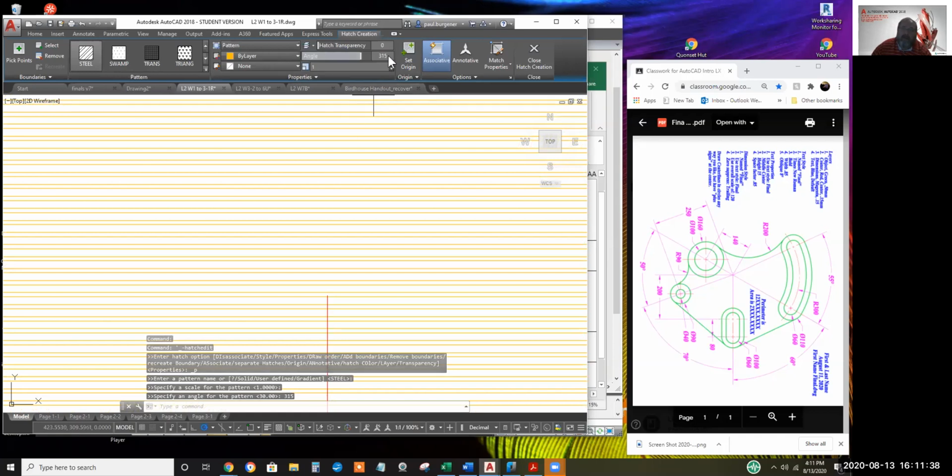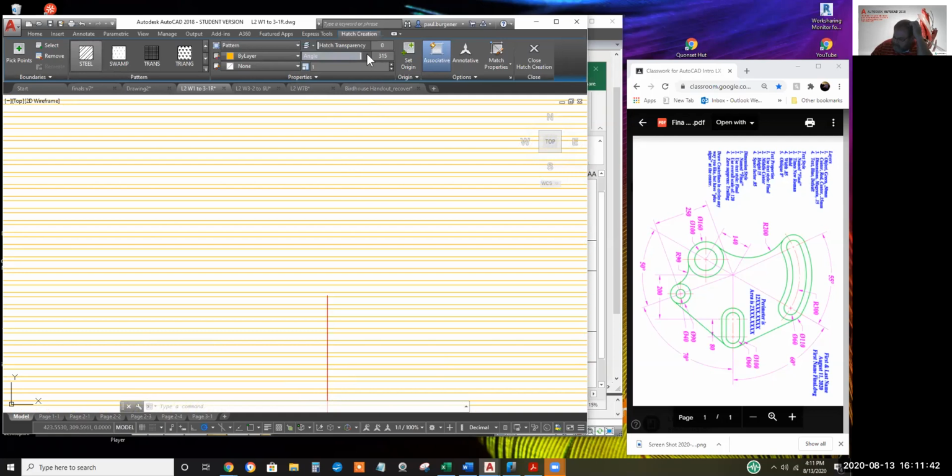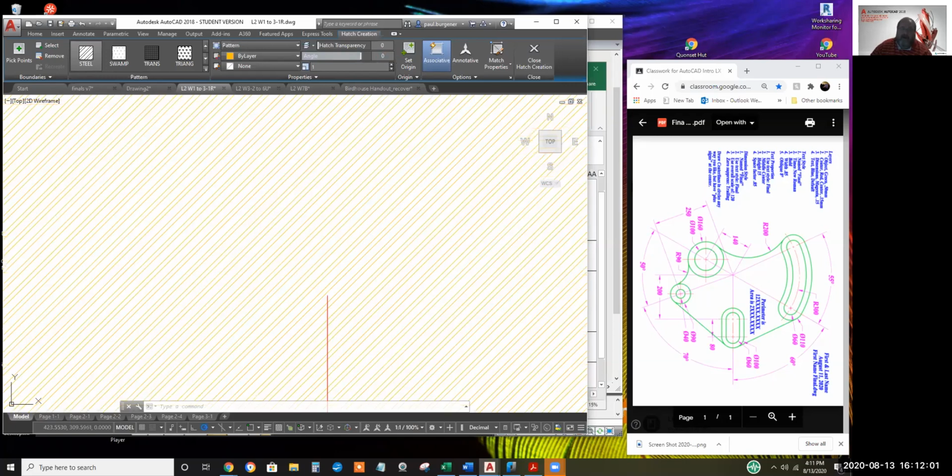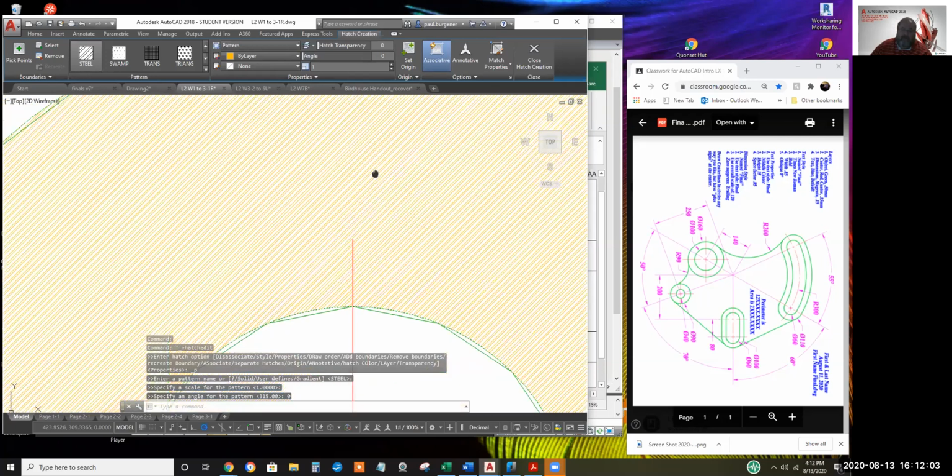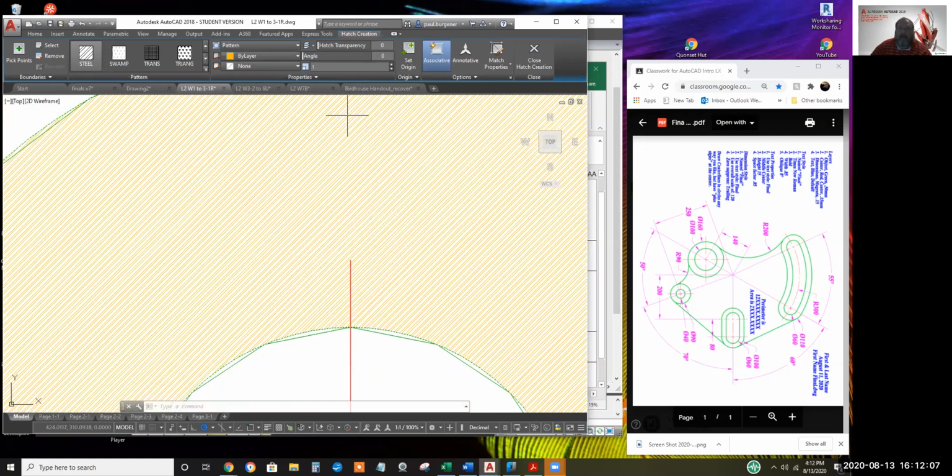And it's good habit if you've got a section view of, like, hydraulic actuators. I recall seeing a cutaway view that showed all the internal parts cross-hatched. It's polite to adjust the angle of your lines for each different part, so it's easier to understand which parts move and which, anyway.